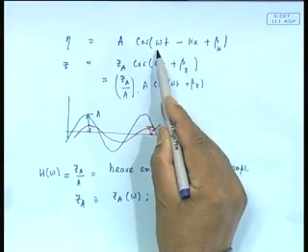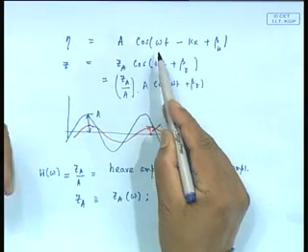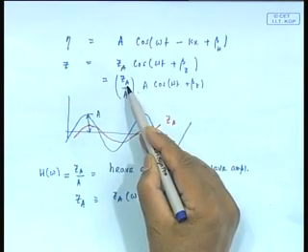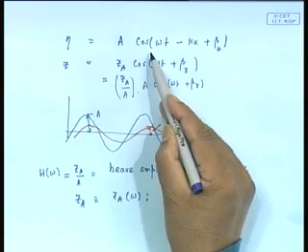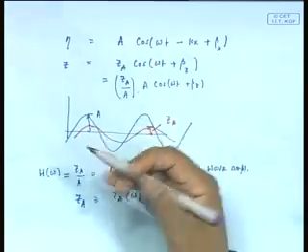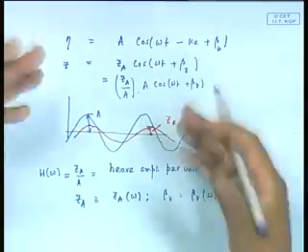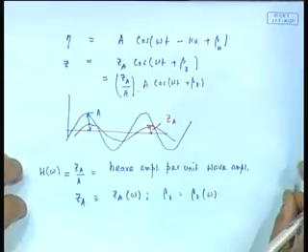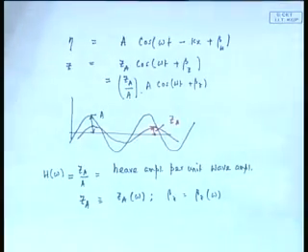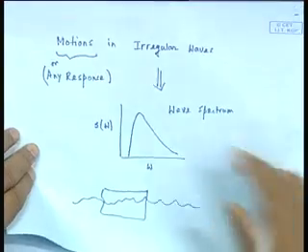Okay. Now, we will come back to this. This we have discussed several times when we talked about response in regular waves. This is what we talked about at the very beginning, single degree of freedom equation, etc. For example, obviously, if omega matches the natural period, then you would expect ZA to be very high. If it is very far from natural period, you would expect ZA to be very small. Therefore, ZA is a function of omega. It depends on what wavelength is there. But the question we are talking about today is, of course, motion in irregular waves.